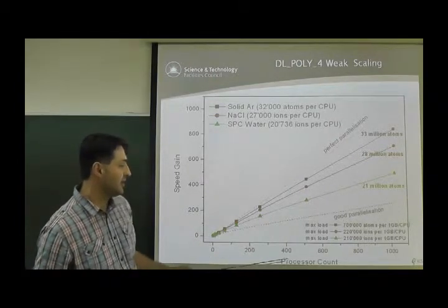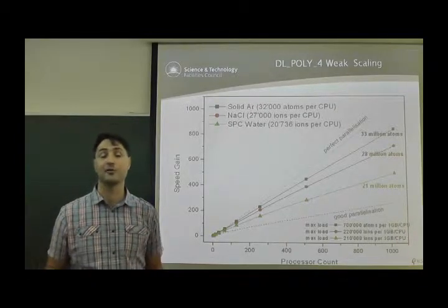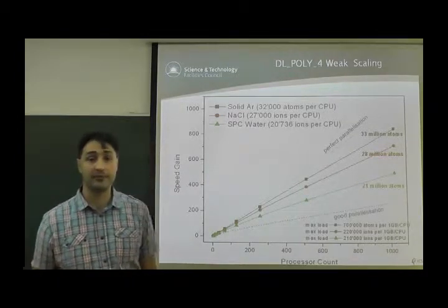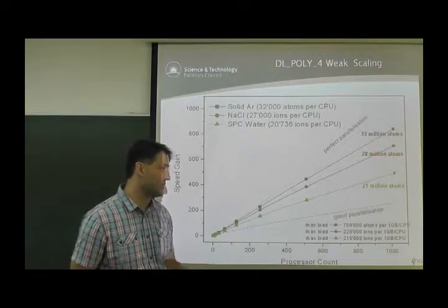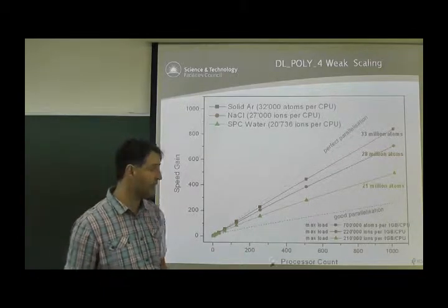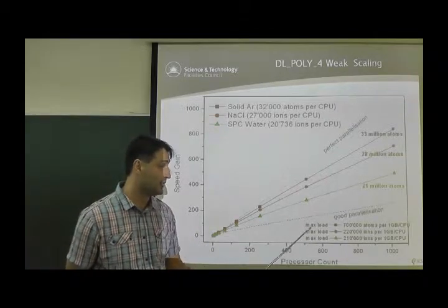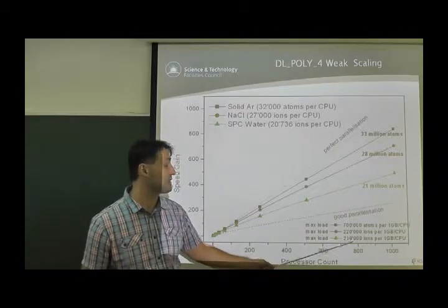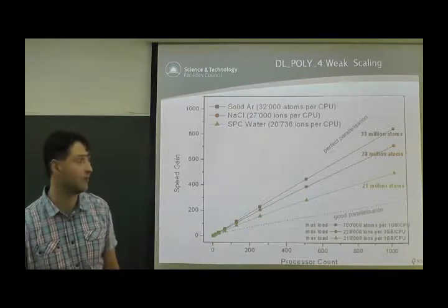It is possible. Let me just mention what the maximum loads are. Quite often people ask, how many particles can I do on one processor? Well, it depends how much memory you have per processor. So for example, if you have 1 gigabyte and you want to simulate only short-range interactions, you can load up to 700,000 particles on that processor. If you include the electrostatics, or electrostatics plus constraints, you can load approximately 200,000 particles per 1 gigabyte of RAM on your processor.